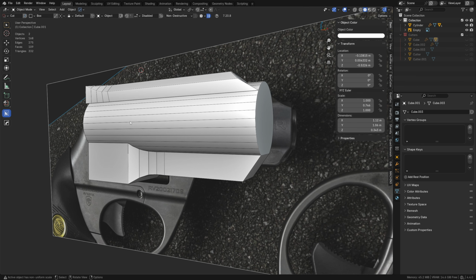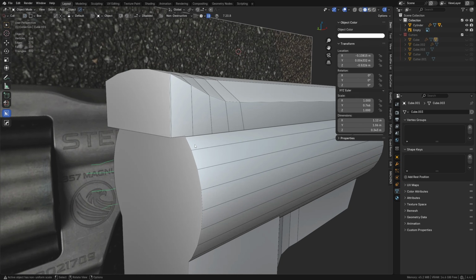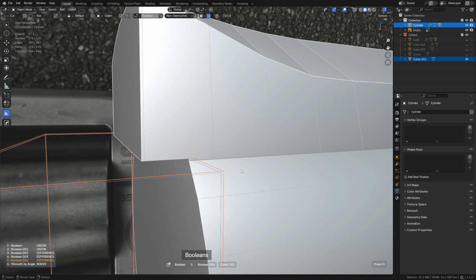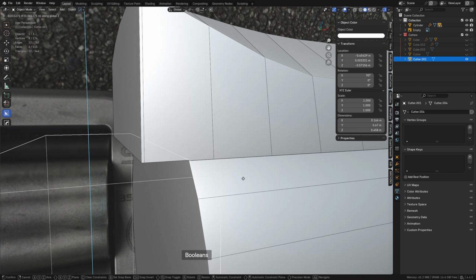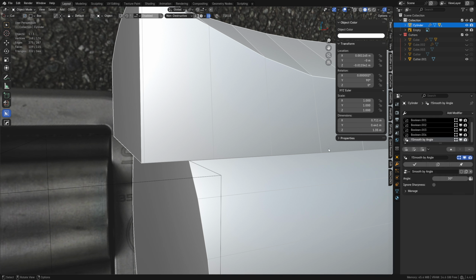as well. If you were really clever with doing booleans, you'll realize that we have some little minor edges that are close. They're not quite there, but they're close. If you get these things closer to your main mesh, you can add a weld modifier and they will weld together.